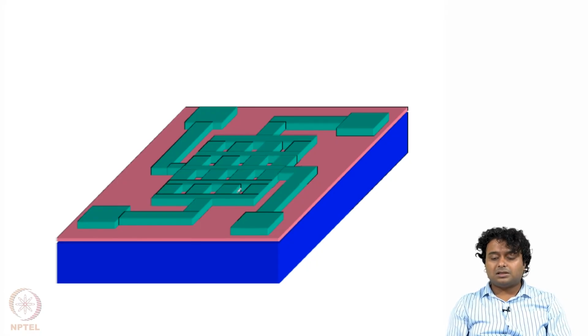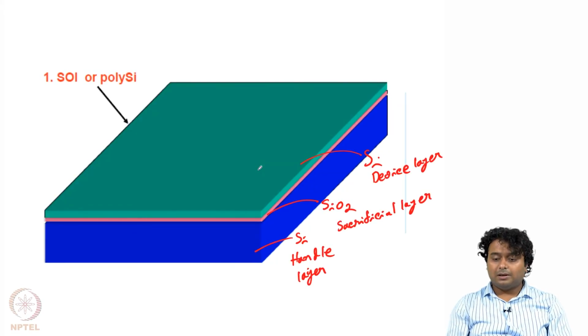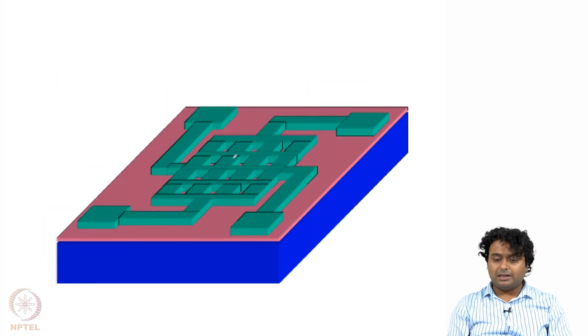Now we have discussed lithography in module 3. There we saw how we can make a pattern on the silicon or on any substrate using photolithography and e-beam lithography. And here you see that using lithography we have etched the silicon according to our requirement or our design, and we have got this structure. After that, if we dip this sample into buffered HF or BHF, then that will etch away the SiO2 part,